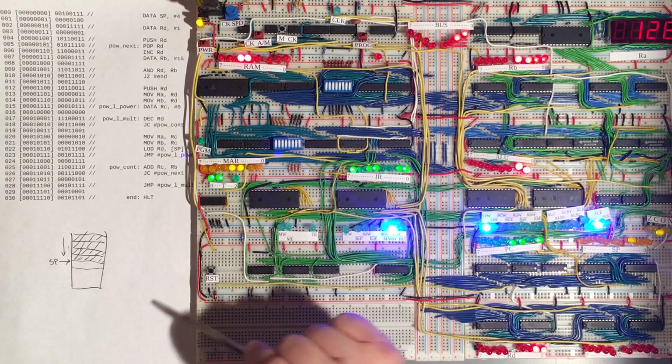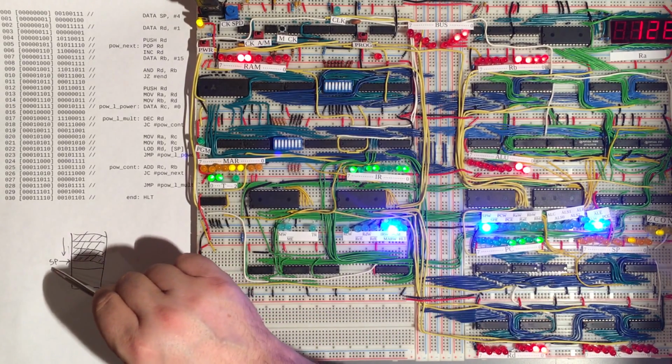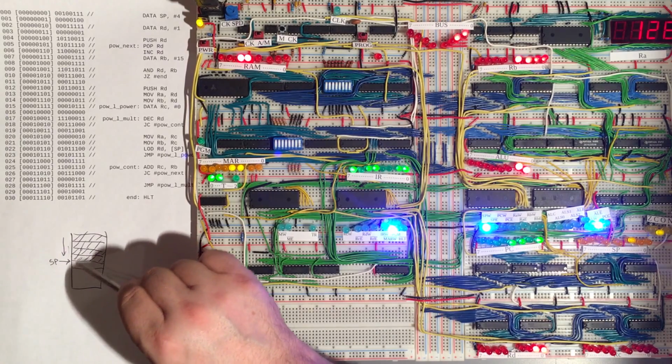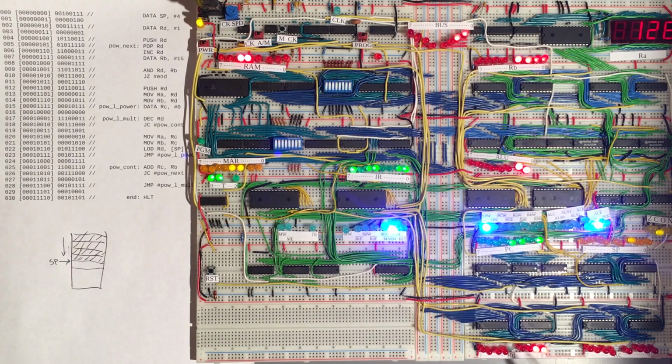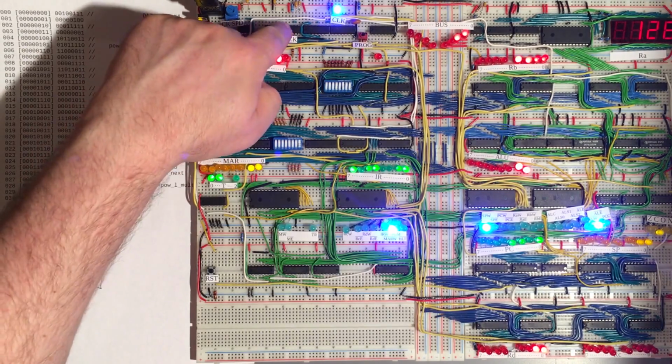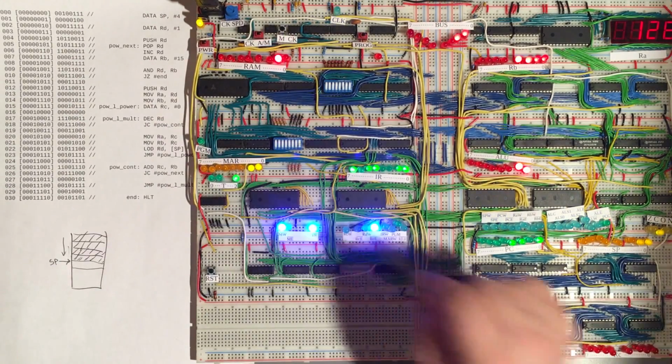And so that way we will have at the same time calculated the new value of the stack pointer, and will be immediately pointing the RAM there, so that we can then finally write this value which we are pushing onto the stack into memory, which is where the stack resides. And so on this next rising clock edge, this 3 here will go both into the stack pointer and into the memory address register. And so there it is.